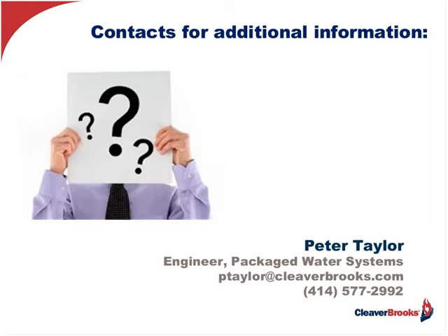Steve, you were talking about a good bit of suggestions for selecting a particular trap, but nothing on really sizing one. Can you go over that just for a moment? Sure. As far as sizing the trap is concerned, first of all, you have to know what the condensate load is in pounds per hour. Then you're going to apply a safety factor, which can vary anywhere between 1.5 to 1 to 10 to 1.